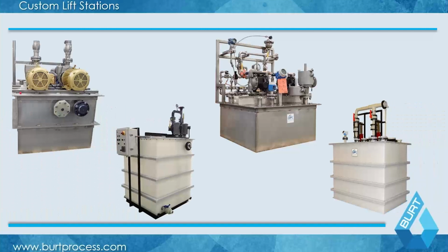That being said, lift stations come in a lot of different shapes and sizes. And the reason I show this is there are a couple of things to know about lift stations, where the nuances come into it. One, it's not just a tank and a pump in these cases. Depending on where your gravity line comes in, this may have to go into a vault space. You may have lower inverts coming in, so you end up with pumps that need to be able to draw to the bottom, or you need a self-priming design.